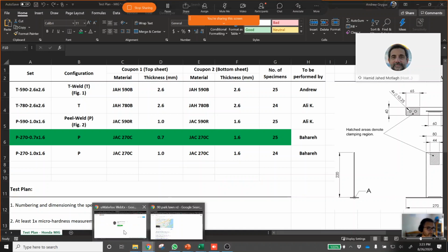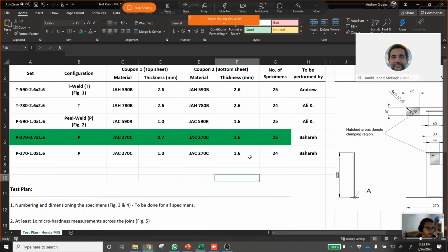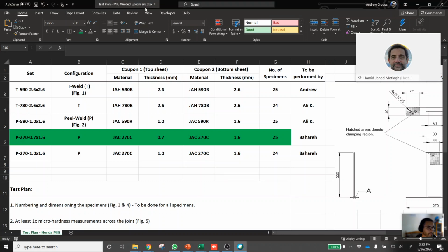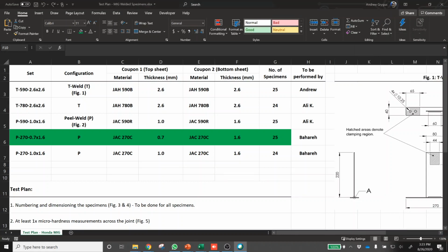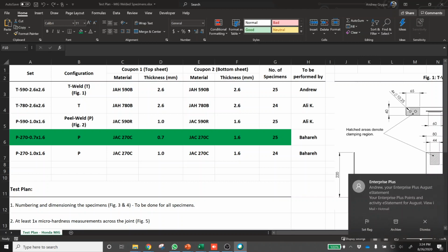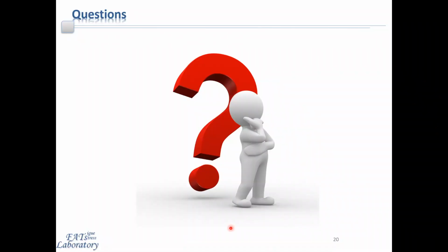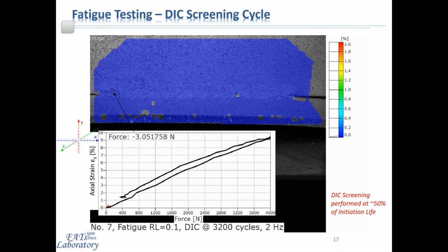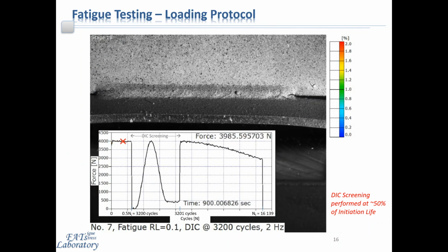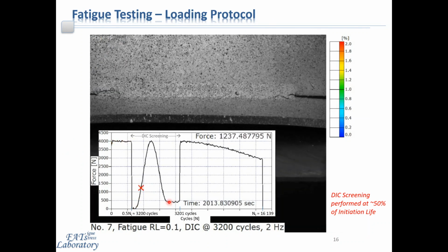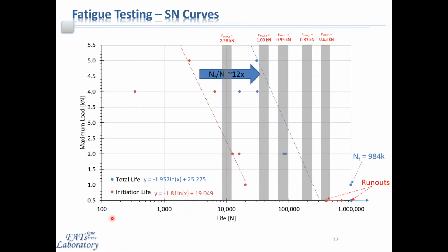As far as residual stress measurement, I think the point that Andrew was showing at the weld toe for strain measurement is actually where we would like to measure the residual stress. Since we have two of those points per each sample, it would make sense that we make a measurement at each of the sides of this weld toe and corner, and probably one in the middle.